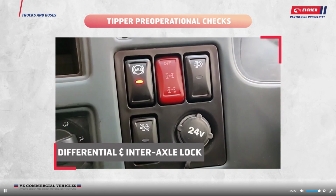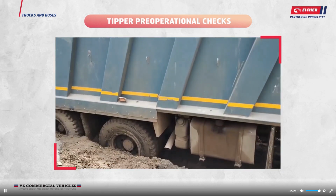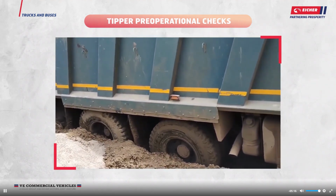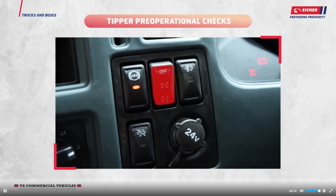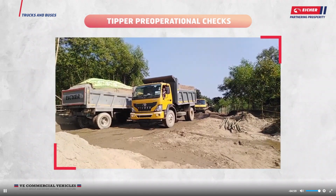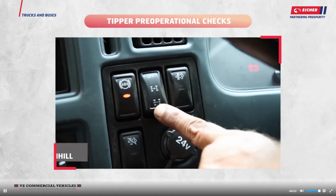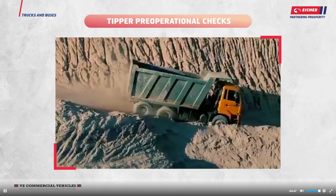Let's understand the usage of the differential and inter-axle lock provided in the tipper vehicles. If the vehicle is stuck in mud or in loose soil and one or more wheels are slipping or losing traction, at that time, engage the differential lock and inter-axle lock by pressing the switches provided on the dashboard. Note that when the differential lock is engaged, the vehicle should be moved in a straight direction in crawler gear. After coming out from that situation, disengage the differential and inter-axle lock. Caution: don't lock the inter-axle differential at downhill or while wheels are spinning.